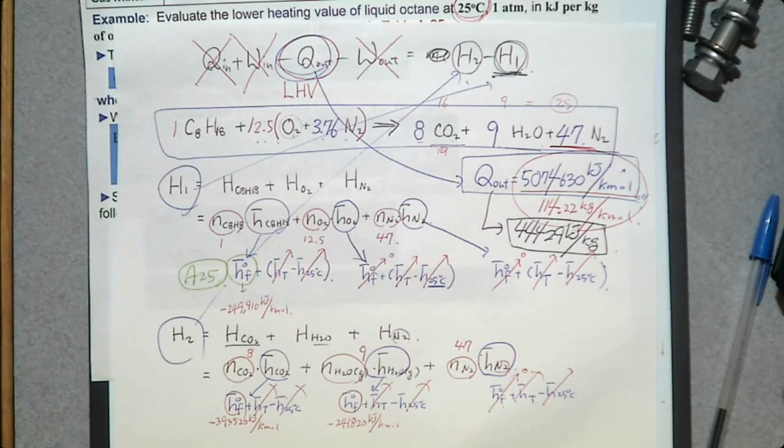When you have a combustion process and at the end you see water dropping from the combustion product, that means more heat is created. When you see water vapor, with no condensate, lower heat is created. So that depends on the condition at the exit of the combustion chamber.